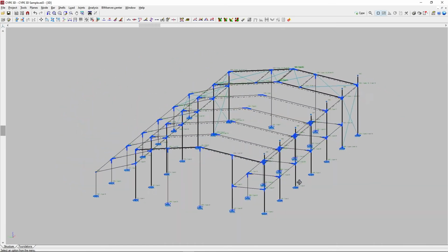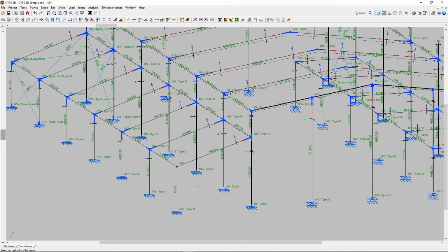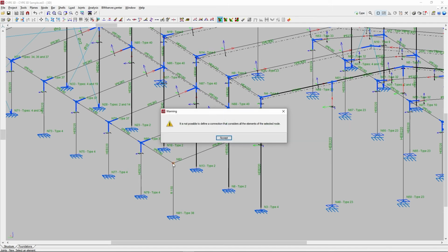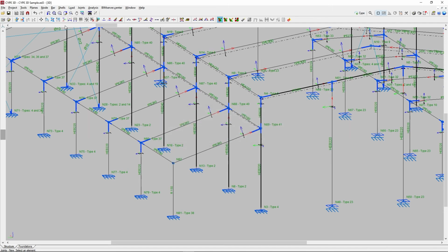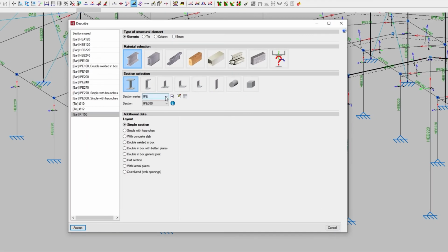The generation of connections depends on the geometry of the intersections, the number of bars in their section, the section layout, the elements created, and whether or not there are pinned connections at the end of the bars. If the program does not generate a connection for a specific point, we can check these details so that the connection defined in the model is matched to one of the connections that the program is able to identify.